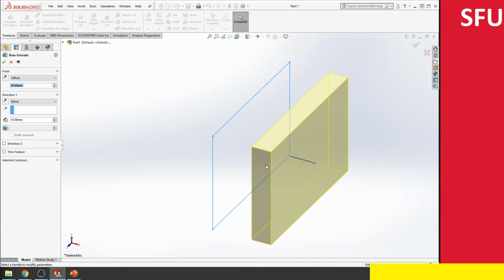So this is our sketching plane, and our object has basically started 20 millimeters from that particular plane. That's based on this number that we set. The next one is direction 1, which is how far we are extruding in the first direction. This says blind.